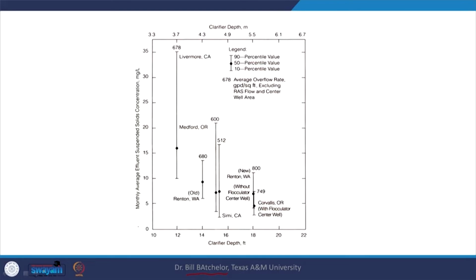So, what do we have out here? Monthly average effluent suspended solids concentration. So, here I have the suspended solids concentration in the treated wastewater, and here I have the clarifier depth, but this is in feet. As you see, even 12 feet, I think 3 feet is approximately equal to 1 meter, right. So, 4 meter here as such, but for these kinds of plants,